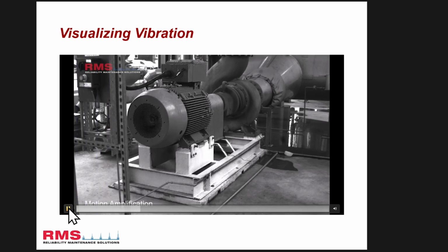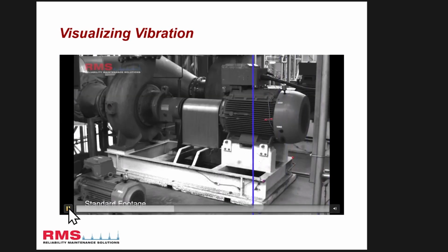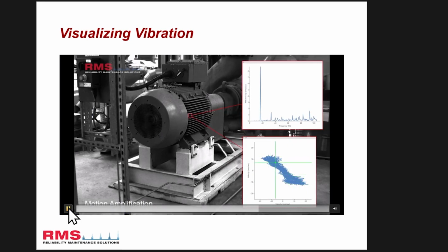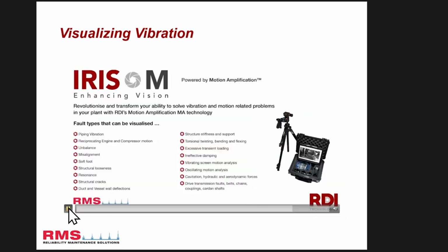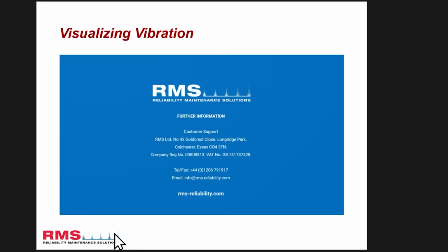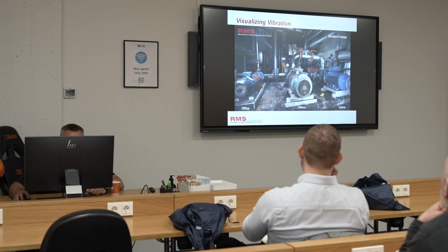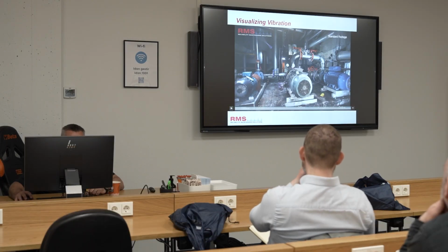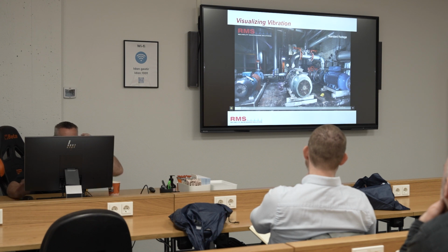When you see the standard motion, the software allows us to look at the standard footage and then put the motion amplification on to see things moving and how they move. Now for us, this is a game changer from a diagnostic perspective, because we would just be getting that signature at the top that you can see there, the spectrum, and make a diagnostic decision on that. But now we're allowed to see through the feet and all the rest of it, really. Just play that again so you can see it.